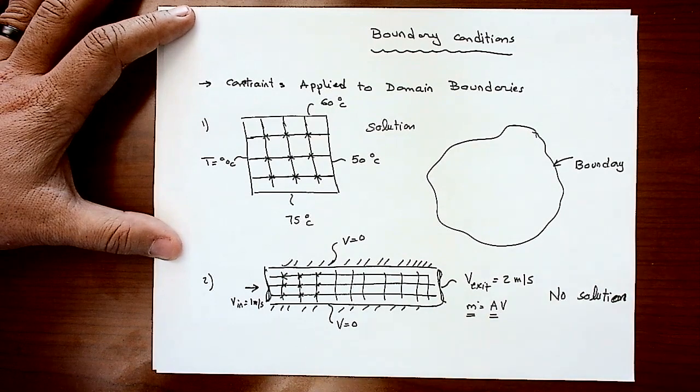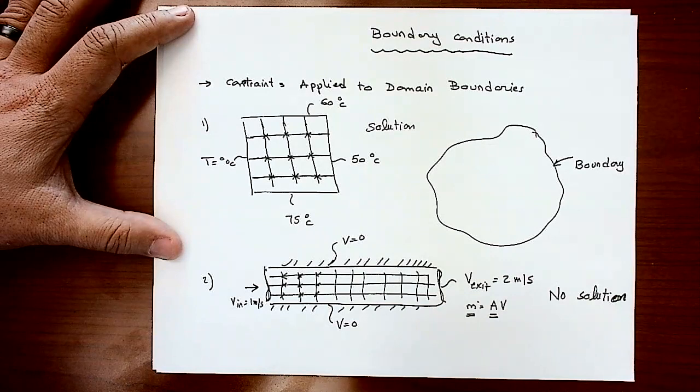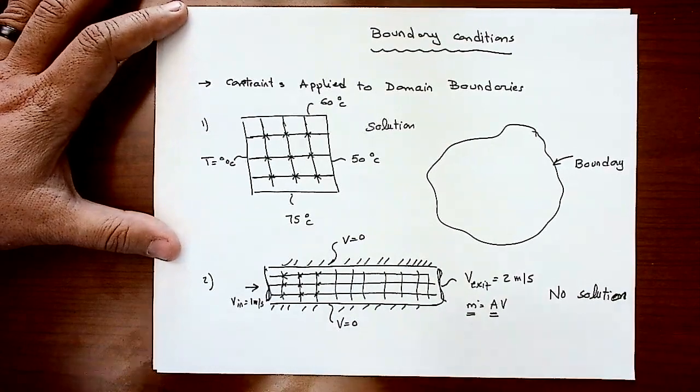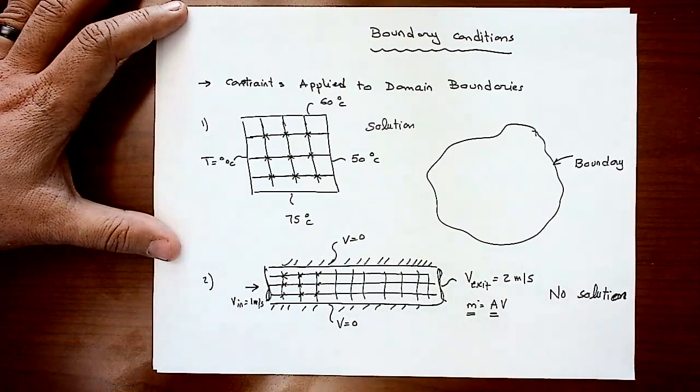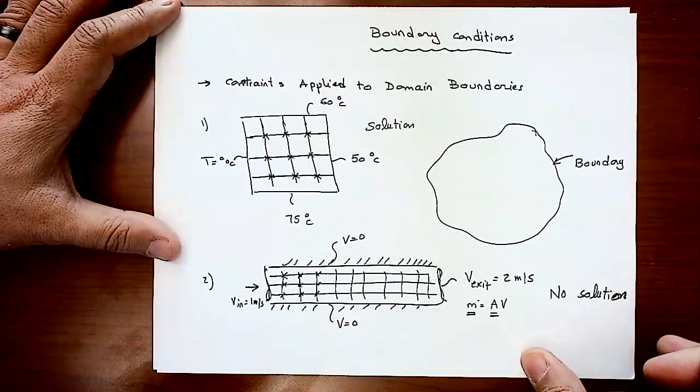So your numerical scheme that keeps solving the differential equation, or the governing equation, will keep rotating about itself and cannot reach that boundary condition. Okay, it's 2 meters per second, or you will get unrealistic data within that domain, which we know doesn't make any sense. So that's how the boundary conditions are very important, because they could lead to no solution or a crazy solution because of the bad assumption that you make at the boundary side.